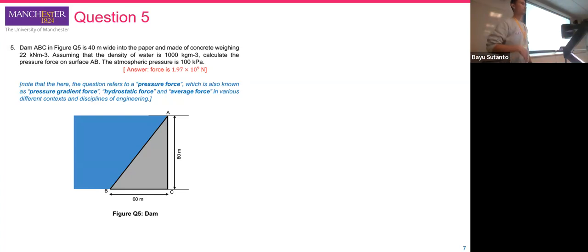There is no change of the atmospheric pressure, but the change only happens in the hydrostatic force. To make it simple, first we can use the center of gravity method, and second we can manually integrate the equation. For the center of gravity method, we can replace the linear hydrostatic force with one single force.